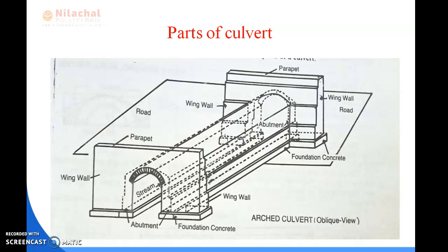In engineering, abutment refers to the structure at the end of a bridge span or dam on which the superstructure rests or contacts. Single span bridges have an abutment at each end, which provides vertical and lateral support for the bridge. It is a masonry or reinforced concrete wall constructed as the end support of the bridge or culvert, by which it joins the bank of the water course.